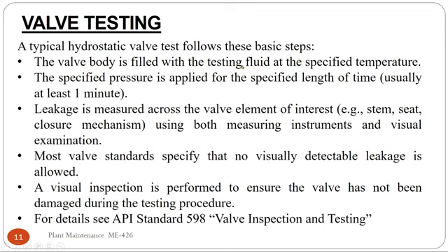Testing fluid means if you are using the valve for water, use water, or if you have to install the valve on a petroleum product, then use petrol at the specified temperature. We will see a video as well, but the video will not be of hydrostatic testing, it is air testing.